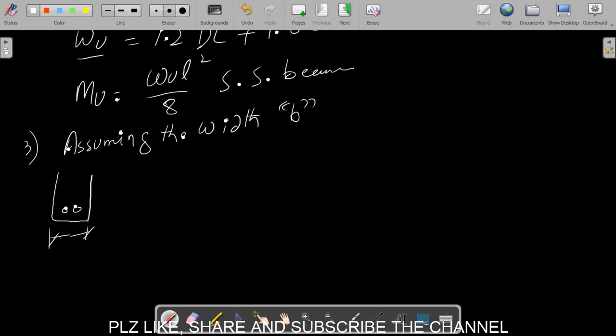And width is usually assumed for a shallow beam as L by 15 to L by 20. So for a shallow beam it usually varies from L by 15 for smaller or shallow beams, and L by 20 for larger beams.